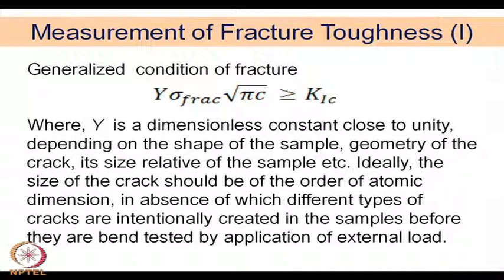Okay. So, you have an existing crack which is created intentionally on the surface, and then you try to find out what is the energy required or the stress required to propagate it further. That is the basic principle on which the fracture toughness is measured.